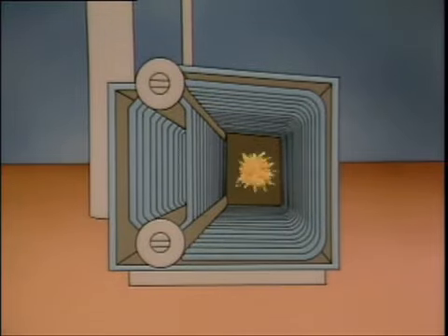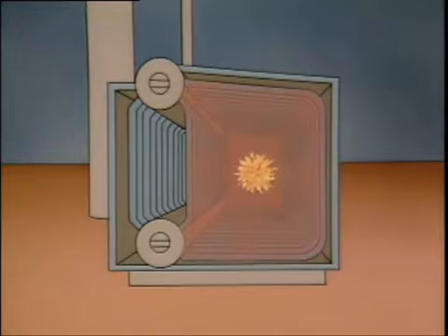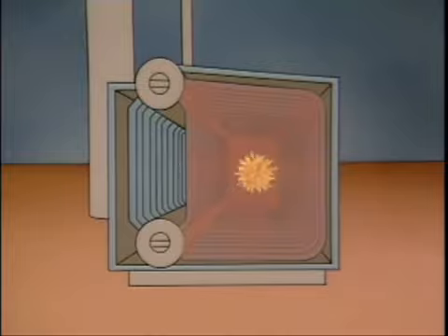The burning fuel also produces combustion gases. As these hot gases pass through the boiler, they transfer heat to the tubes as well. This is convection heat transfer. As the outer surfaces of the tubes absorb heat, conduction heat transfer occurs. Heat is transferred from the outer surface to the cooler inner surface. Then heat is transferred from the inner surface to the water flowing through the tube.